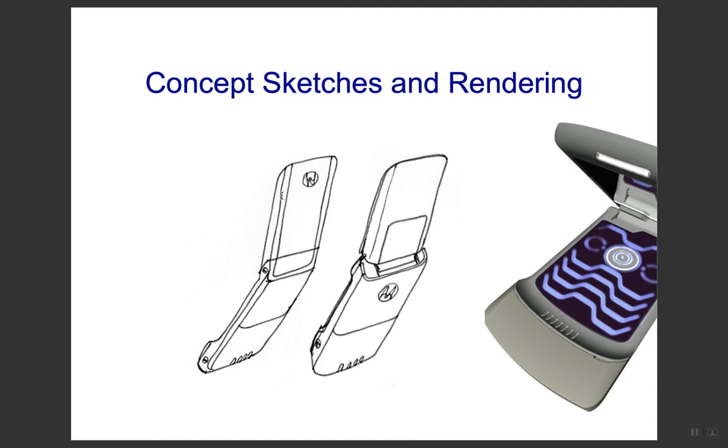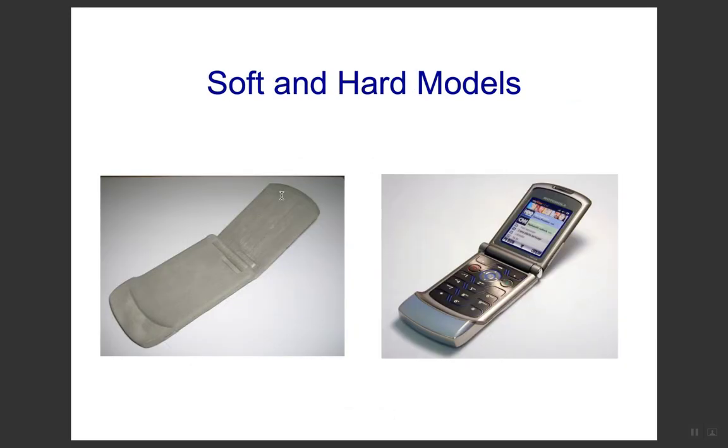I think you have understood this, right, guys? From the customer needs, then concept generation, followed by sketches, renderings, and this is the prototype, or we call it a dummy. You see that the size is the same but the material is different. Of course, it does not reflect the functions, but it reflects the appeal or appearance.